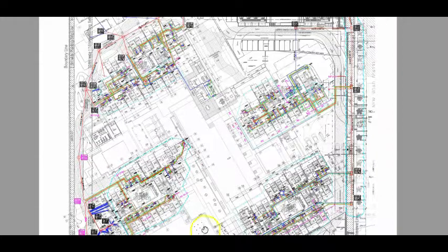This is the typical sanitary piping for the condominium project. All the sanitary piping from the units runs down from the riser to the basement high level and combines to the sanitary main, going to the IC at the first story. This applies the same for all the blocks.